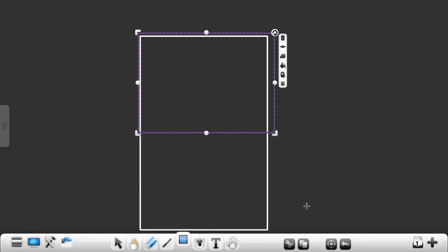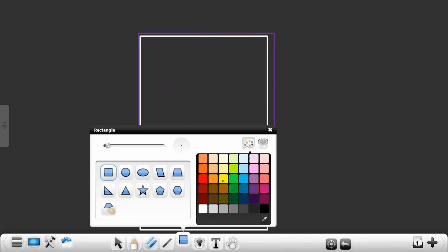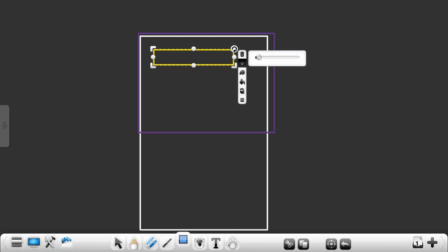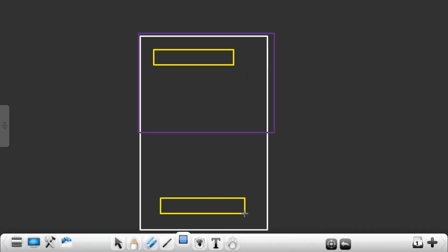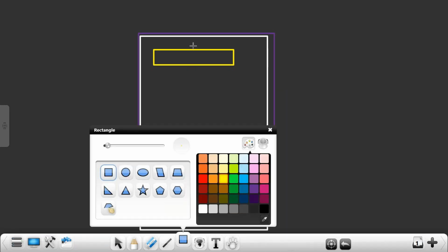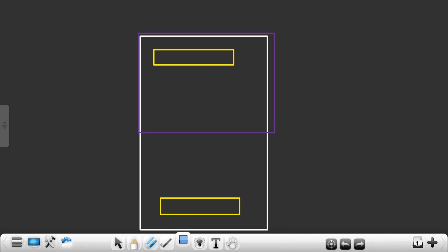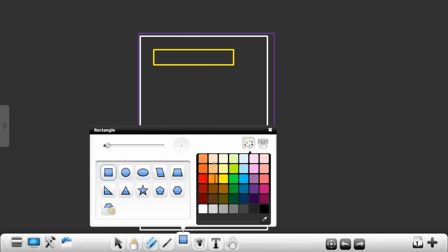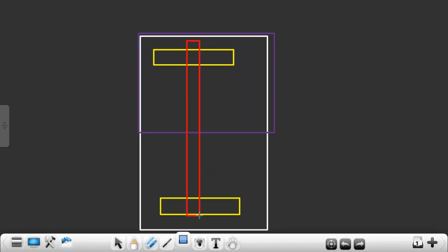This purple color is the N well. So inside the N well, what is formed? P diffusion. Here you have N diffusion. In between P diffusion and N diffusion, you have polysilicon. For a CMOS inverter, both gates are shorted, so I will write only one polysilicon.